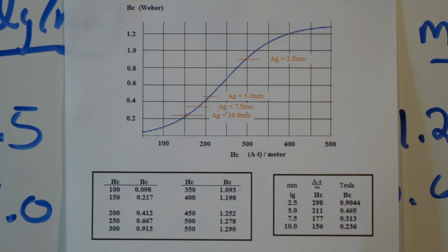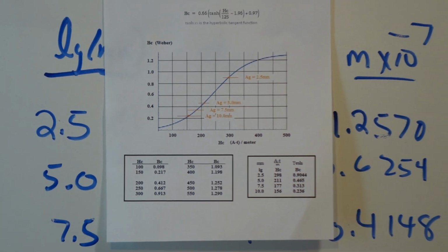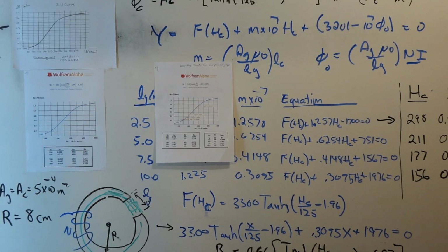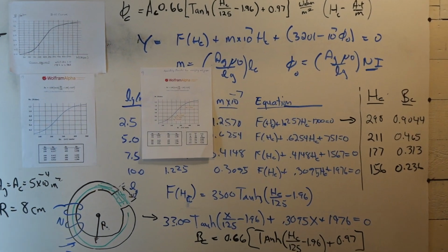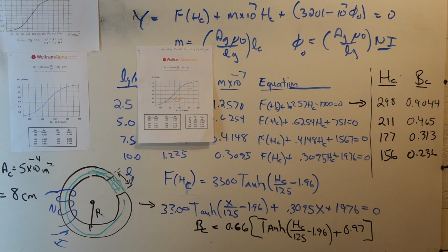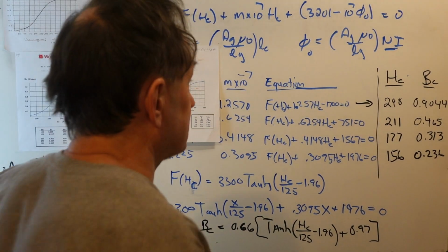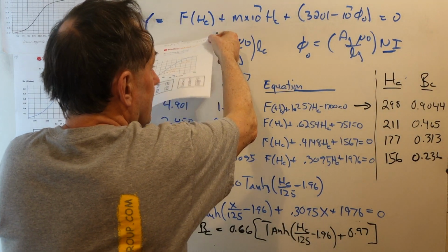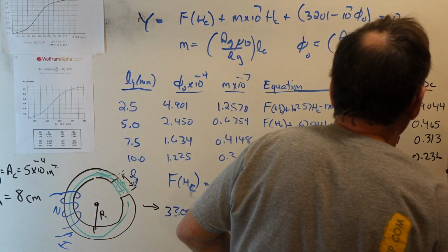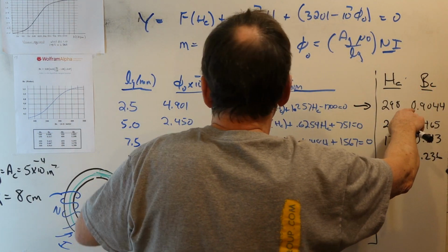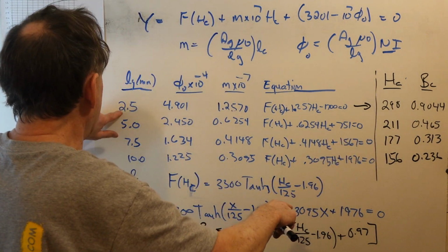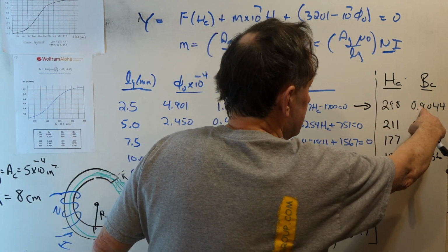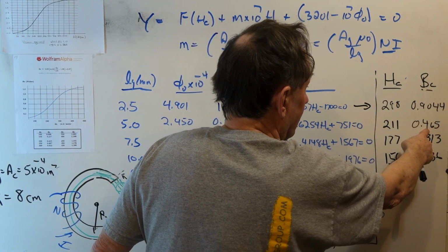as we might expect, because remember, most of the ampere-turns are dropped in the gap. So we would expect a linear relationship in our H or in the B field as we change the gap length. Doubling from 2.5 to 5, we can see that the B field drops by about half.